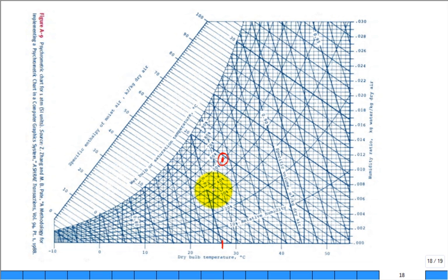And where are we at after we go through? We're at the constant humidity ratio, 0.1114. And we're going to come out at what temperature? We're going to come out at a temperature of 45, which is right here. So there's state 2. State 1 to state 2.